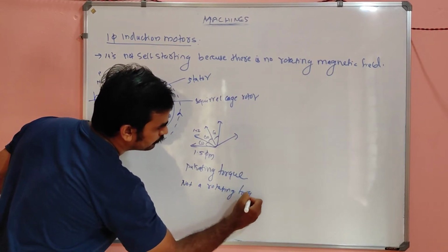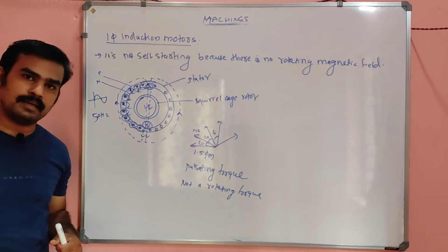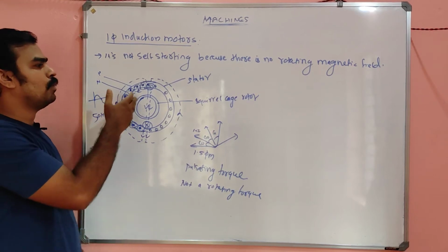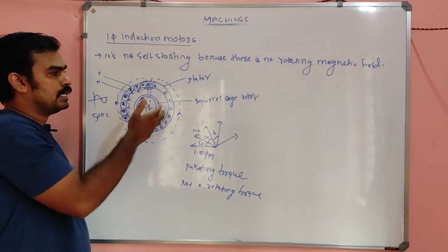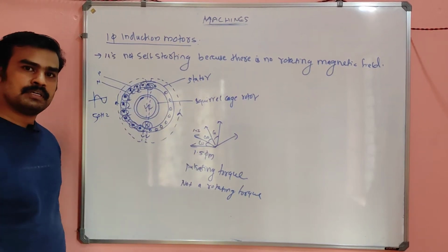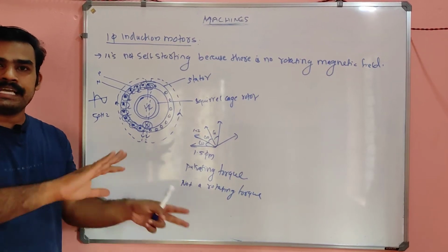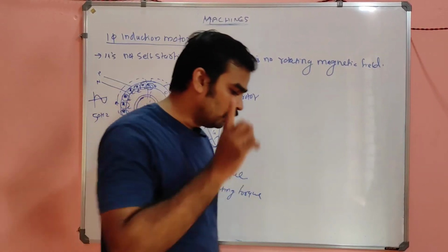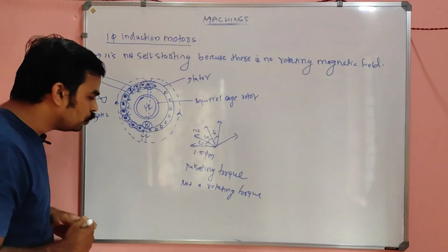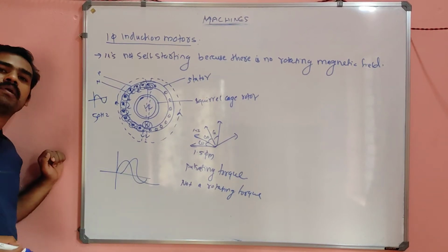It is simply a pulsating torque that happens there, not a rotating torque, my dear. Even if you make a stator of 4 pole, 6 pole, 8 pole, or 16 pole, there will be simply north and south changing, pulsating, not rotating. For a rotating magnetic field, at least you need 2 waves, my dear. Then only there will be a rotation.